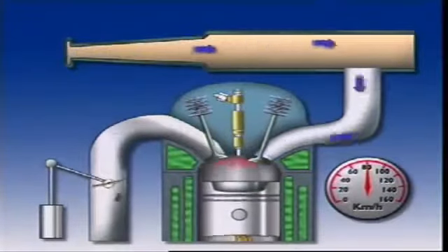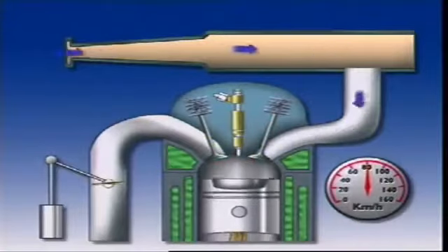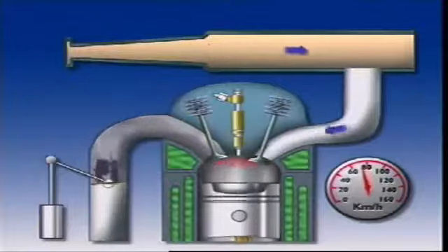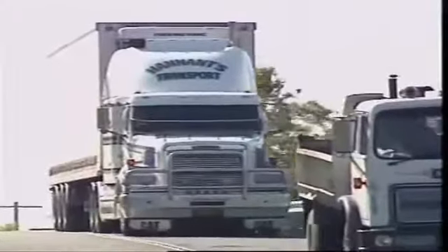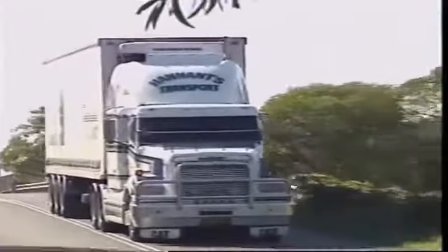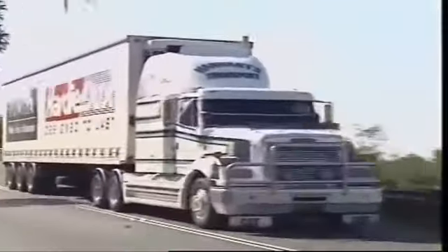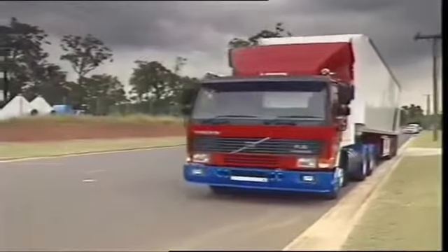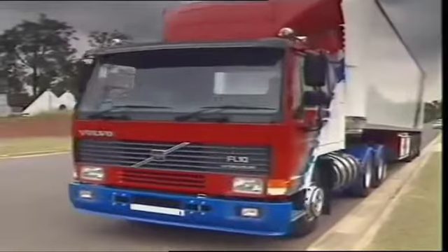This maintains high pressures in the exhaust manifold and the engine cylinders, which in turn acts as a brake against the engine rotating. This then slows the road wheels through the transmission or powertrain. Other heavy goods vehicles use an engine brake that operates by altering valve timing and stopping fuel being injected into the engine.